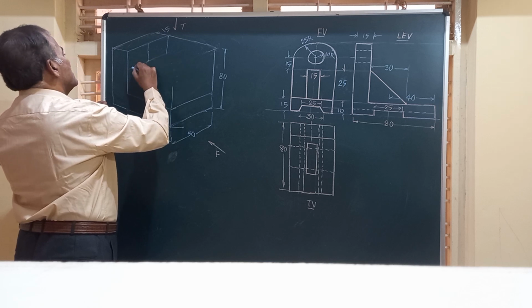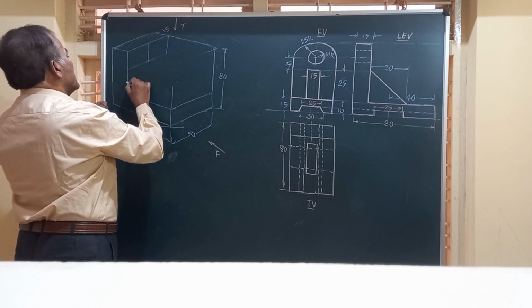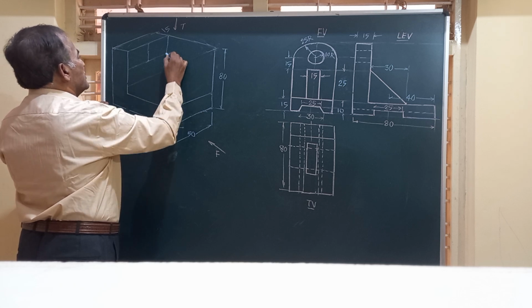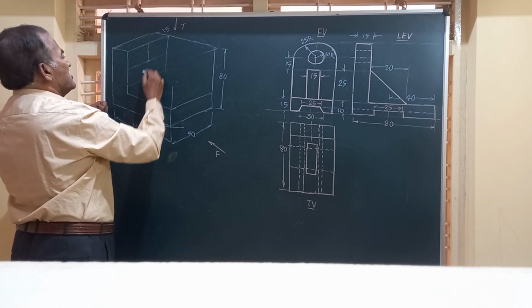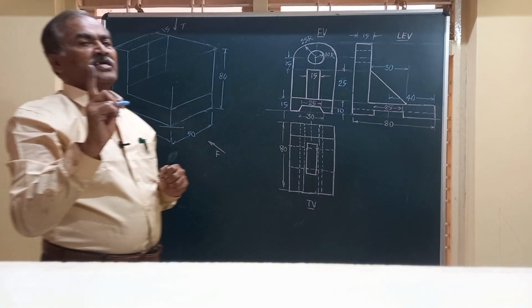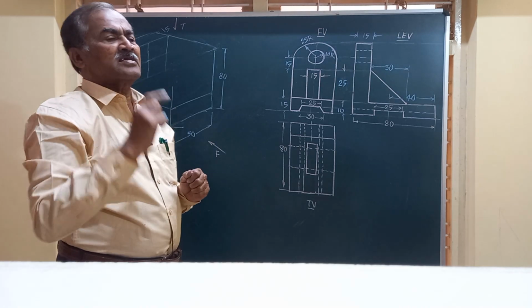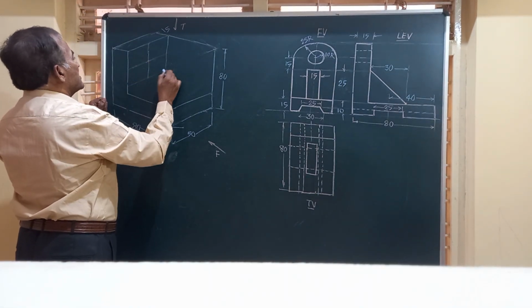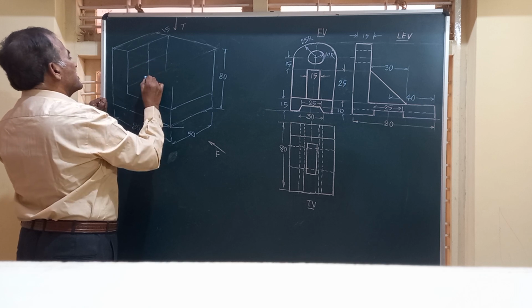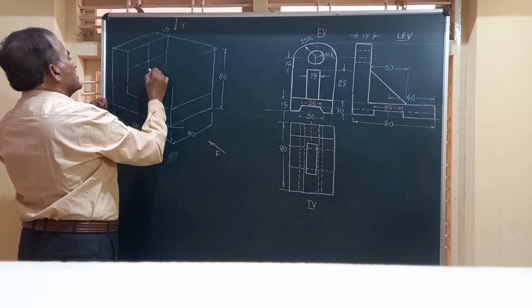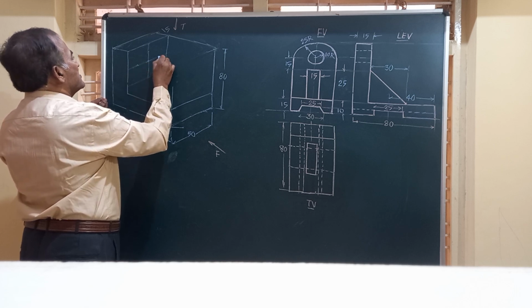So friends, you know the procedure. You can have it extended by the other distances, whatever the height you have got here. I am going to make use of the four center method to construct the semi-ellipse. So friends, I have got this box completed, and from here I am going to join this point to the center of this, and similarly this to the center of this.